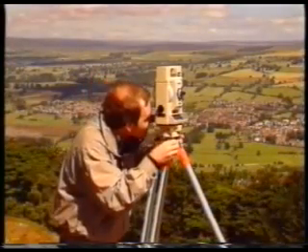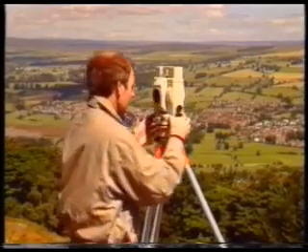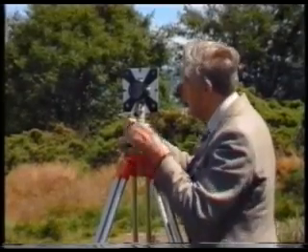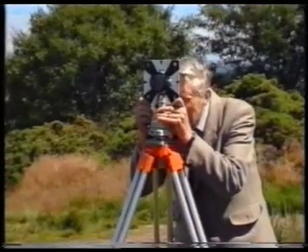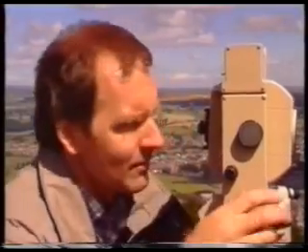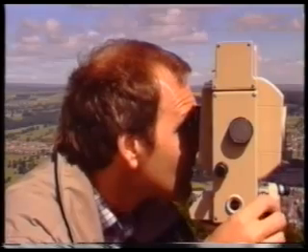Consider the measurement of a line AB. A combined EDM theodolite system is carefully set up over point A, and a reflector is set up over point B. The sights on the reflector are used to align it with the EDM system. Parallax is removed, and the center of the reflector is sighted.